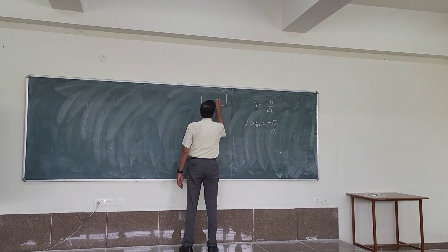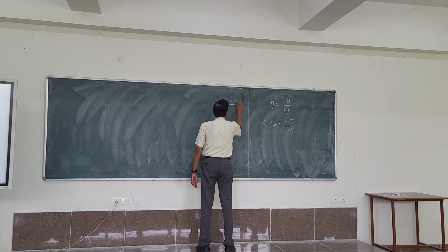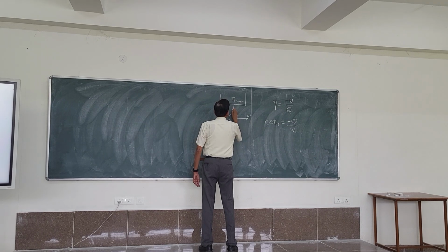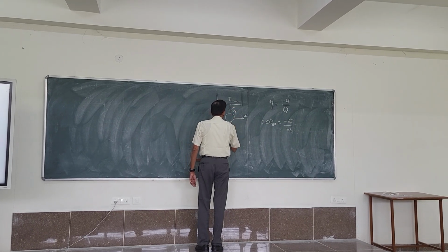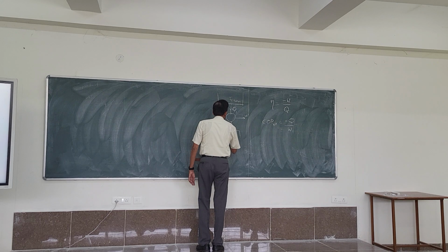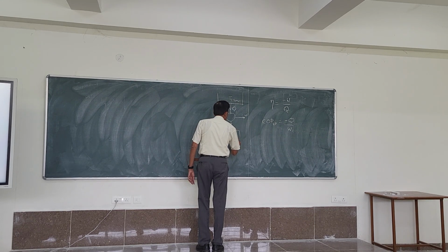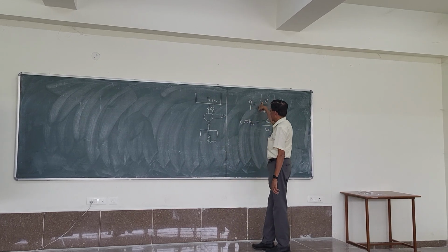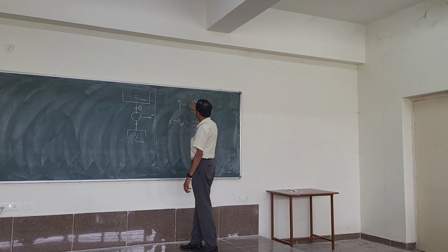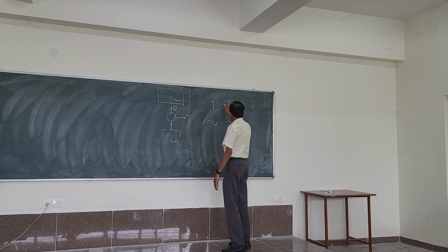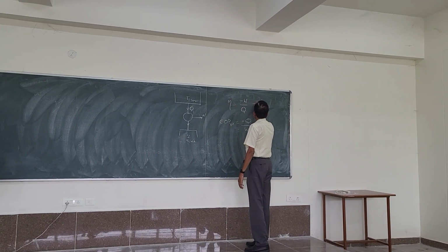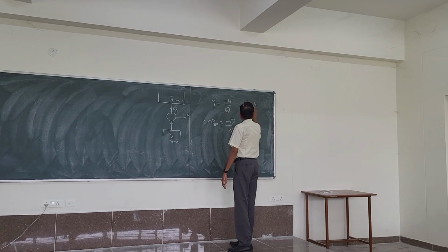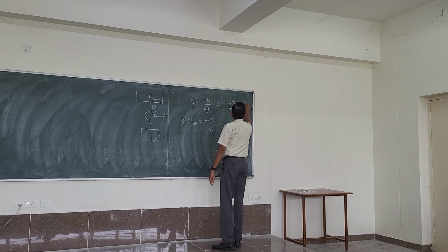If it is working with two sources, this is the source and this is the engine. This is called W. This is the amount of Q1 coming from here, this is the amount of Q2 going out from here, and this is the temperature T2, which we call the sink. This W will obviously be minus, so we have a minus sign there, and minus of W with this minus sign actually makes it plus. So we have efficiency, and we found that this efficiency is nothing but T1 minus T2 divided by T1. It can also be written as 1 minus T2 by T1.